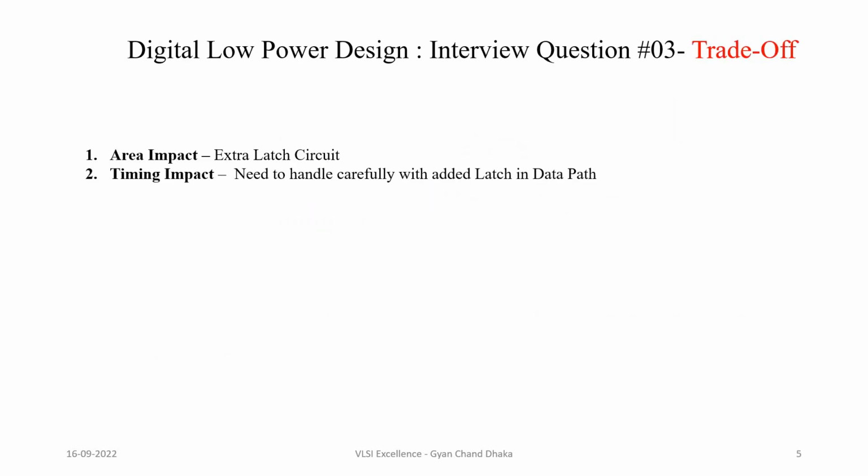Now let's see what the trade-offs of this solution are. Of course, there is an extra latch circuit we have to keep in the data path that will definitely increase the area of the design, and because of the added latch in the data path, we have to carefully handle the timing of this path as well. So these are the trade-offs associated with this particular solution.